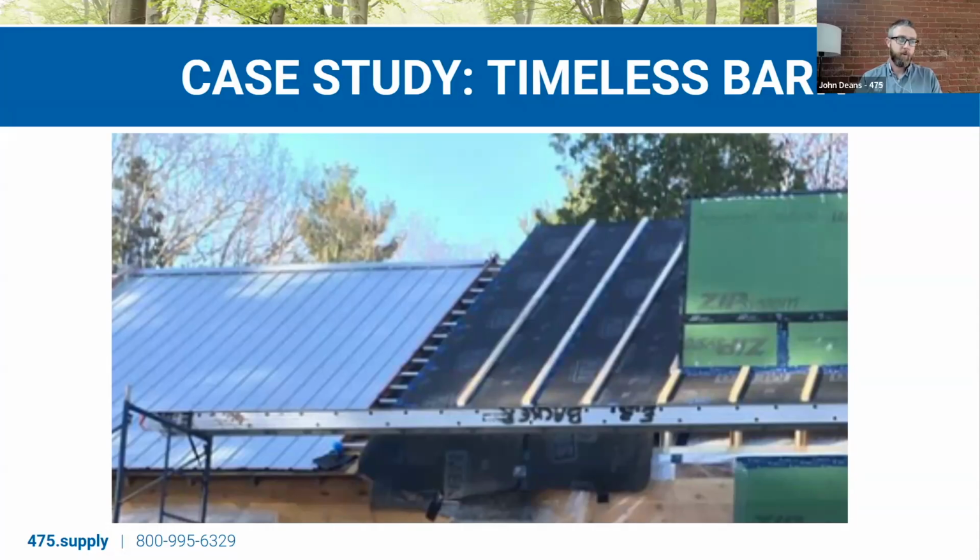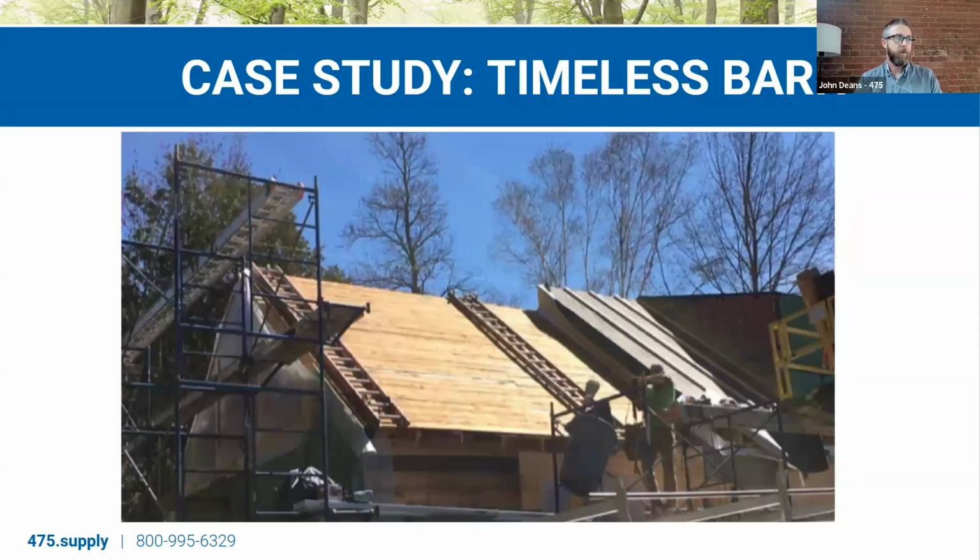We would strip a section, build our assembly, and then move on to the next section. This is showing the backside of that board sheathing. We stripped it down to that, and then we put a black underlayment, something like Fronta Quattro, which is UV stable, so that when you look up at the ceiling, you don't see anything but just dark black lines.